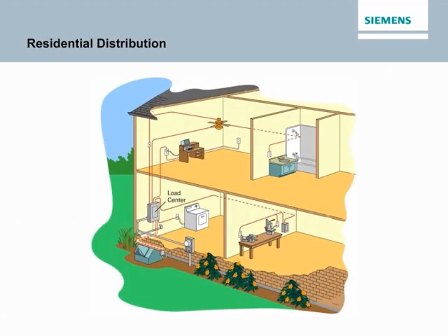The incoming power then goes to a load center, which provides circuit control and overcurrent protection. The power is distributed from the load center to various branch circuits for lighting, appliances, and electrical outlets. Sometimes, particularly when there has been additional construction, a second load center, often called the subpanel, may be installed and powered from the main load center. Careful planning is required so that the power distribution system safely and efficiently supplies adequate electric service for present and possible future needs.